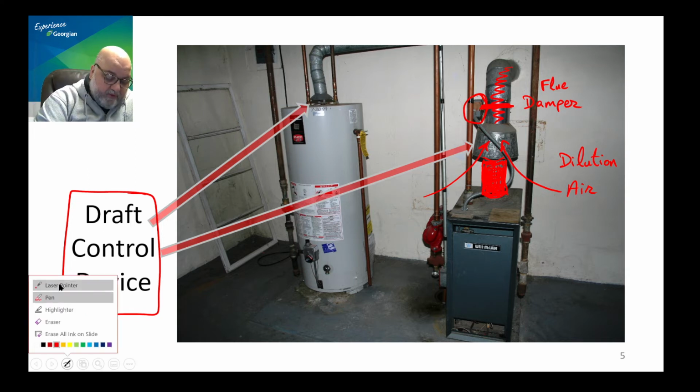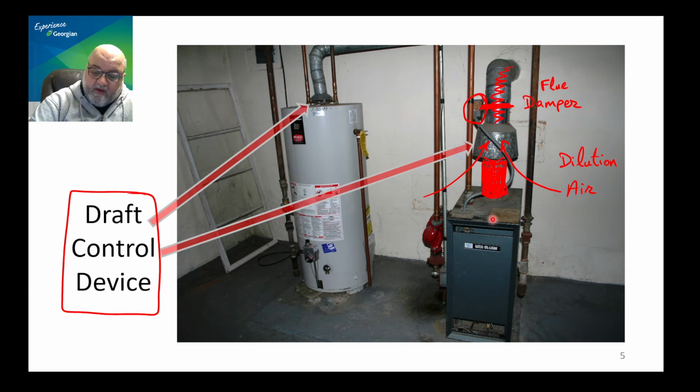are running the boiler regularly, it will have off cycles where the flame is off, but there is a big amount of heat inside the boiler. The boiler has a high heat capacity, and that heat will simply travel up because hot air rises into the air. That's not something you want. You want to keep the heat inside. It's okay if the hot air in the boiler just travels through that draft control device to the outside.